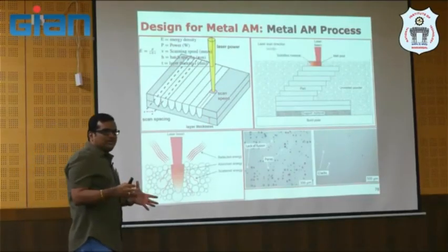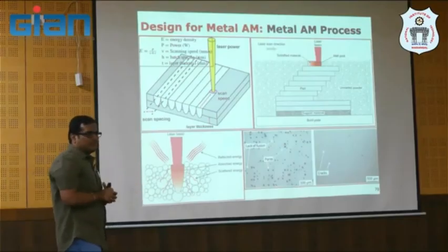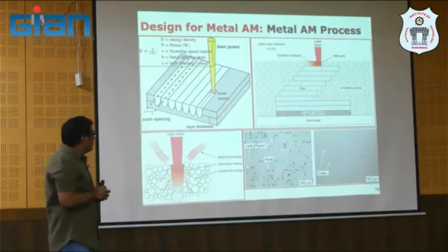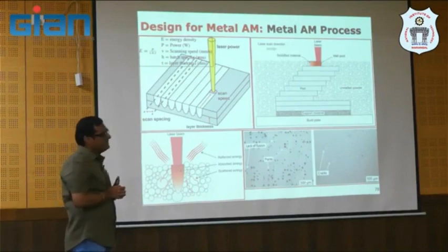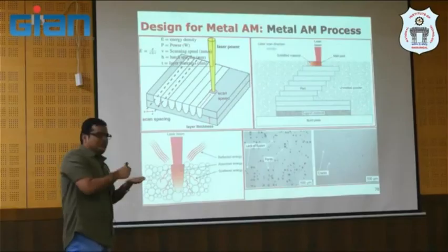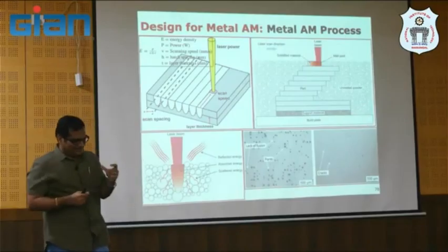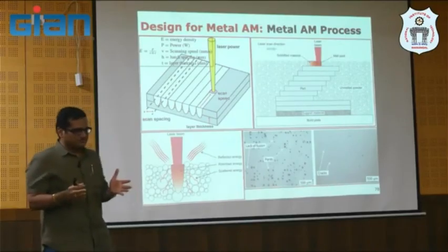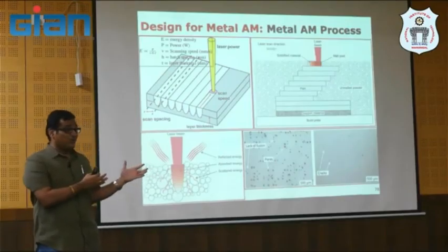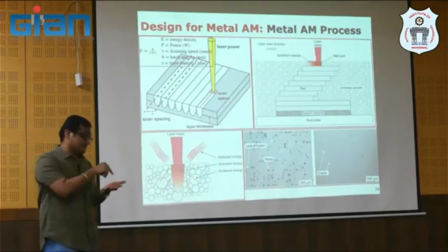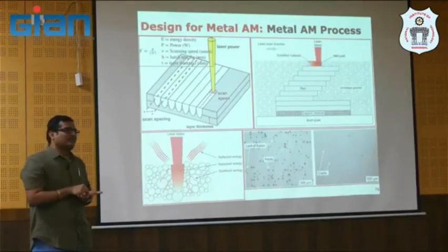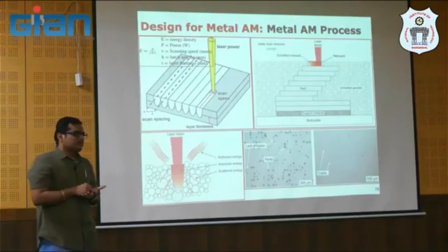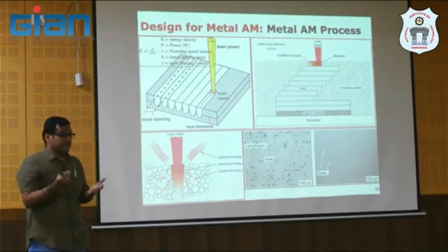I am assuming everybody knows about the powder bed system, right? Energy density is going to play a major role here. Even though we have only a 100-watt laser machine, we have successfully done titanium, aluminum, cobalt chrome, and 17-4 PH.